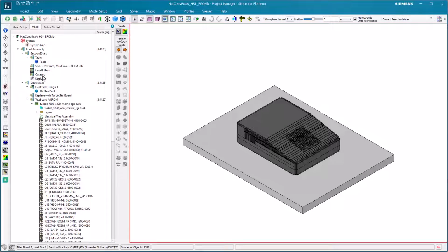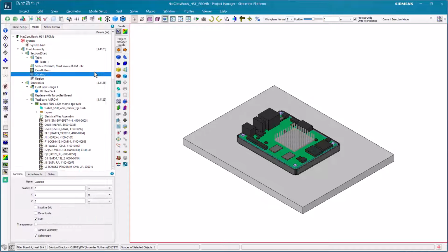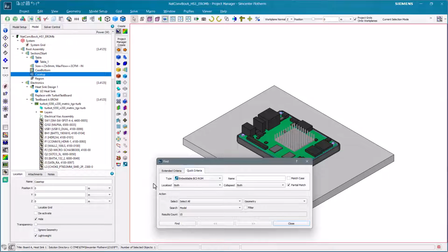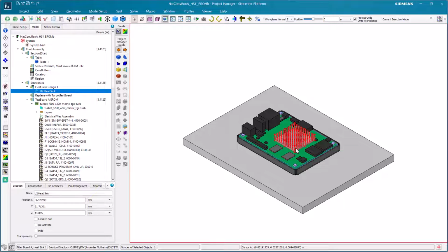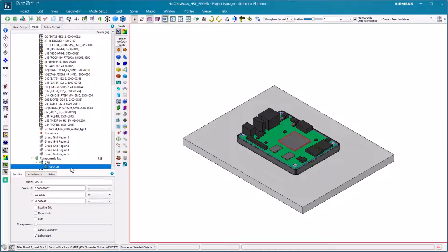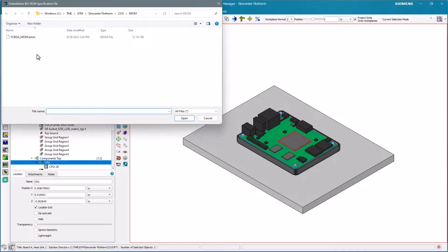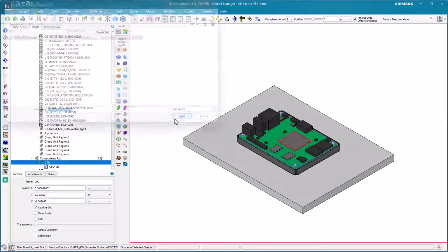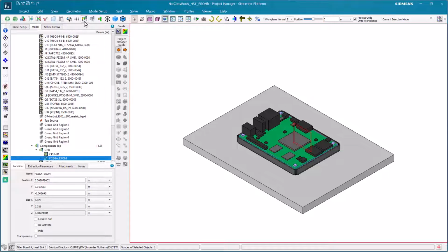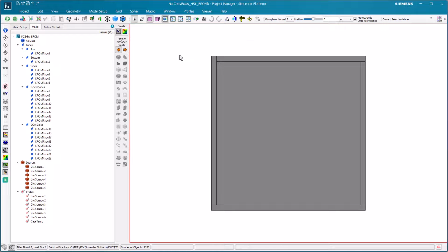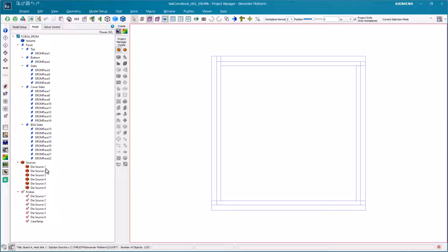Once the embeddable BCI ROM has been created, it can now be used in any system-level design in Simcenter Flotherm. The Simcenter Flotherm model currently has 15 embeddable BCI ROMs, with an additional one to be imported for the CPU. The embeddable BCI ROM is imported through the Smart Part interface. The model consists of the solid volume, heat transfer faces, sources, and probes.